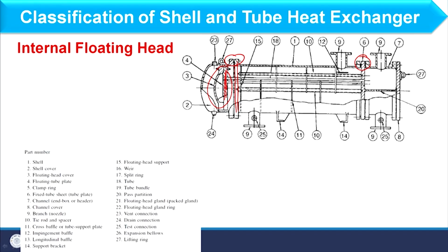Now, what will happen? This tube sheet corresponds to the tubes which are inserted in this. Fine. And if you consider this tube sheet, it is basically providing this much area for thermal contraction and expansion. Okay. So, this complete tube sheet can move in this direction or can move in this direction depending upon the temperature it accommodates. Okay. So, what is happening over here? The complete tube sheet of the tubes is lying within the shell diameter. If I consider this, this is the shell diameter, and the same diameter you can find over here also. I hope it is clear. Okay. So, you see, this is basically the shell diameter and the same diameter is lying over here. Okay. So, the complete tube sheet is lying within the shell.